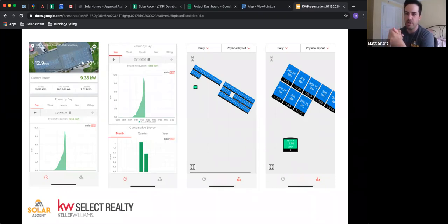In March, we see really great production. We see a bit of a dip in April, typically. Then in May, we start to see it ramp up into the full summer production, and it'll go strong right until mid-October. Part of the reason is solar operates best at 25 degrees Celsius. On a nice sunny day in March, the roof temperature is going to get pretty close to 25 degrees, so the system operates really efficiently. In the summer, you'll get a bit of loss, but you get longer daylight hours, so it makes up for any loss due to excess heat.